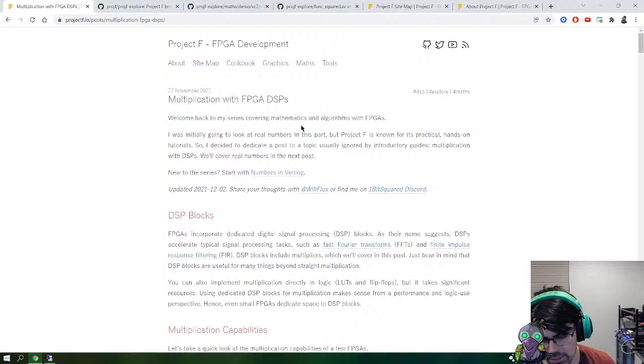We will know about the other primitives, the DSPs, the block RAMs, the UltraRAMs. Sometimes there are FIFO primitives, the IO primitives. Sometimes you'll have primitives for PCIe and stuff like that, or even the special debug features. For Xilinx, there are a lot of unique debug features with JTAG, BSCAN, the DNA register, stuff like that. If you're aware of the capabilities, you can figure out some really fancy uses.